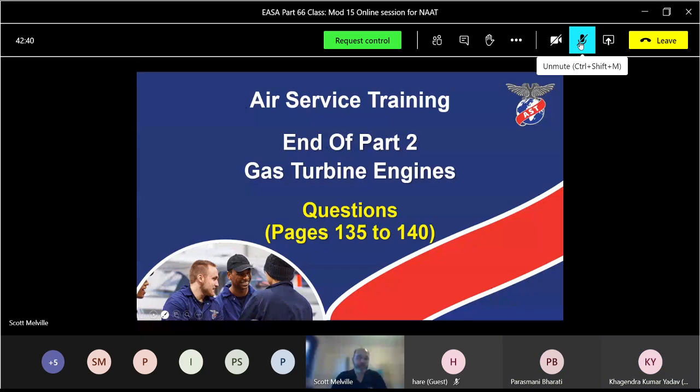Air sealing. Yeah, do you remember the type of seal it's called? Not multi-air. Labyrinth seal, yeah. So it's like a zigzaggy type, abradable seal. There's a rough bit in the top and a zigzaggy bit in the bottom, and as the air pressure gets pushed in, because of the shape, it's like divergent, so it builds a bit of pressure. The oil tries to escape out, but because the air pressure is blowing it back in, it stays within the bearing until the oil goes back to the tank again. So we call that a labyrinth seal or an abradable seal, supplied with air pressure tapped in from the compressor.